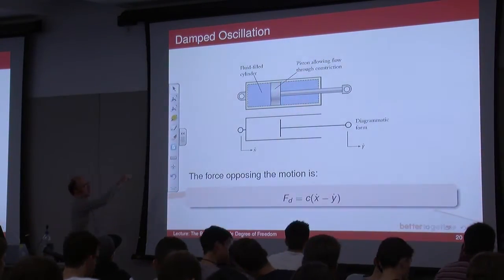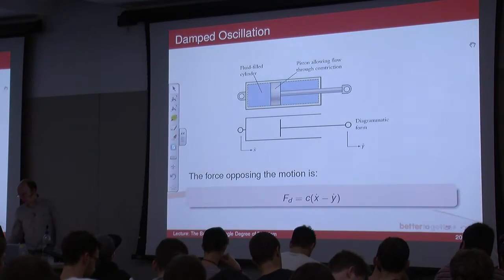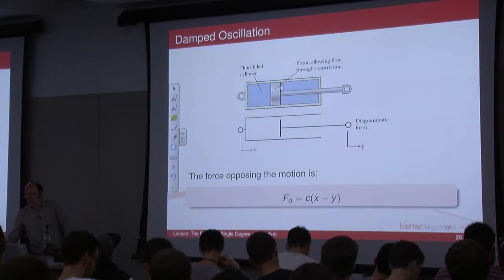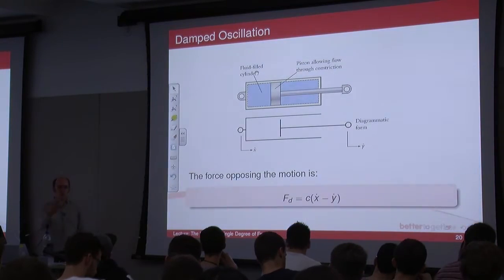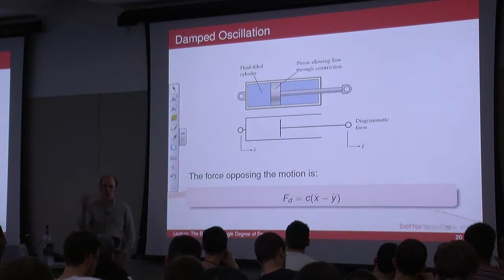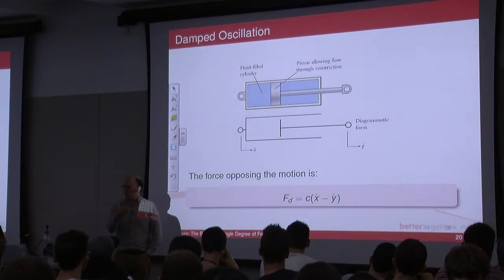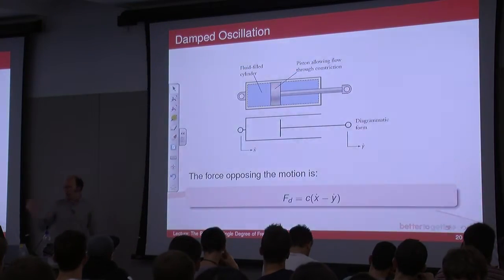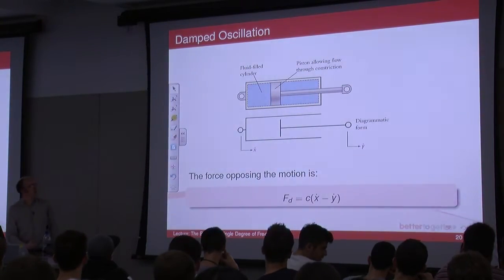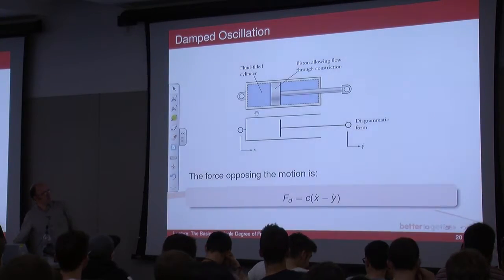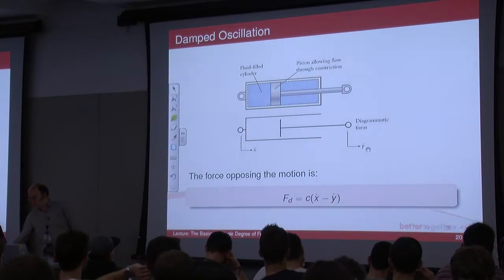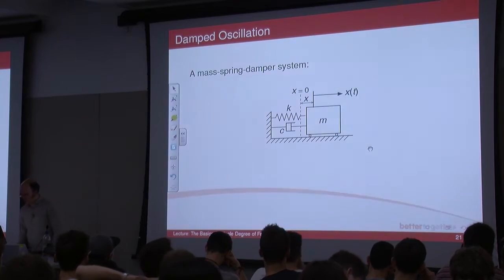So that could be shown as a real damper. Often, up here, you'll have some sort of orifice through the piston so fluid can go from one side to the other. And we all know from level 1 fluids that orifices cause a restriction, and that restriction will control how quickly that piston can move through the fluid, which is obviously causing you damping. This is a schematic of how dampers are drawn, and you'll see that quite frequently.